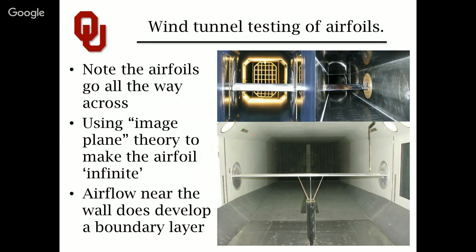But the fact that they travel from wall to wall means that the air flowing over them sees zero end effects. You know, aside from the fact they have giant aluminum plates strapped to that one, and they have big winglets here for that. You know, nothing is perfect. You do the best you can in a test environment. Actually, this scenario here earns a red star because they probably seemingly did the best at incorporating that test airfoil section.